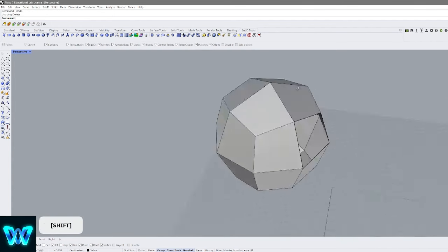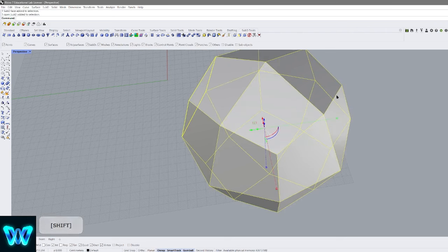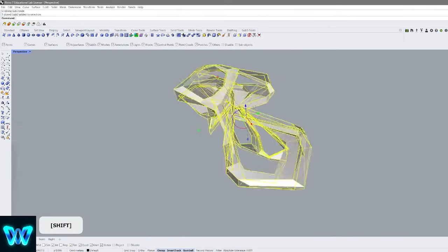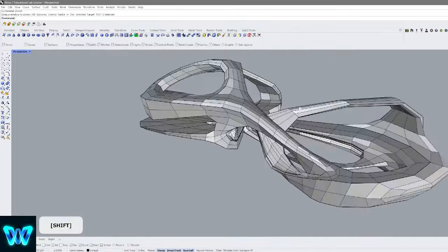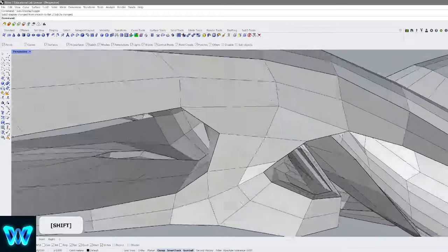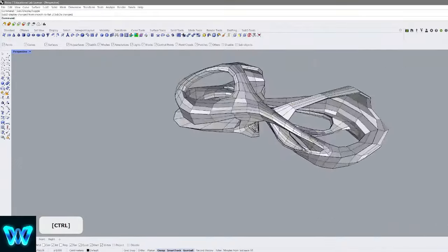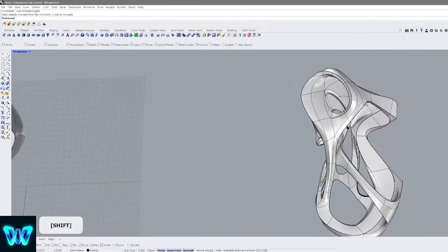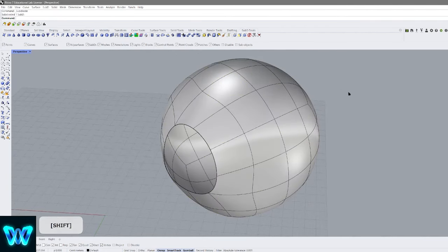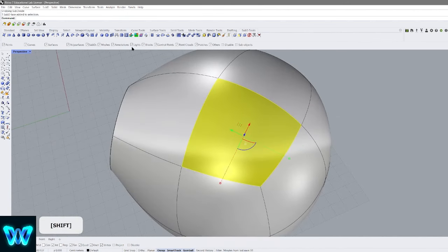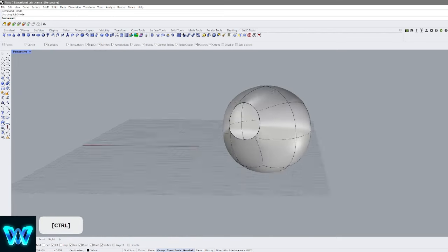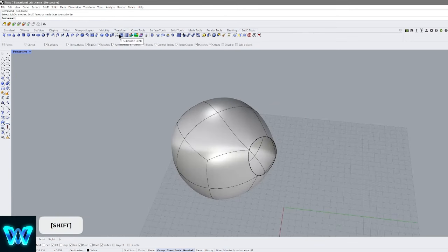You can keep this the old examples. All this does is it takes a face, or it takes the whole SubD and it subdivides it even further to add detail, right? So for example, if I were to do that on this one, it might be a mess, but it just takes you closer to that subdivided form that you already had. And now you're able to add more details that maybe you were thinking about adding before. But I don't like to do that, at least on this, because there's no more detail I need to add on this. But if, for example, these are not enough polygons and I just need more, I can just add more. And at the same time, I can also do it on singular faces. So if I want more faces only here, there you go, I subdivided, and now I can edit that specifically, right? It's pretty useful. And same, it works on meshes too.